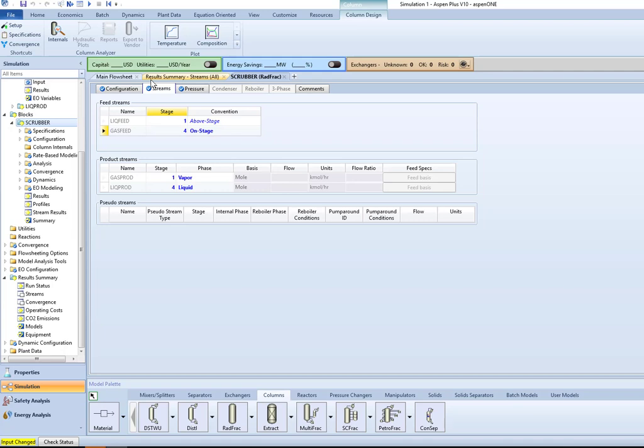You can try adjusting temperatures, so maybe try 80 degrees. Is that better or worse? Or maybe 20 degrees, go cooler. Play with these various compositions. You might try changing the pressure. Okay, you could change the flow rates of the liquid compared to the gas stream and see what happens.